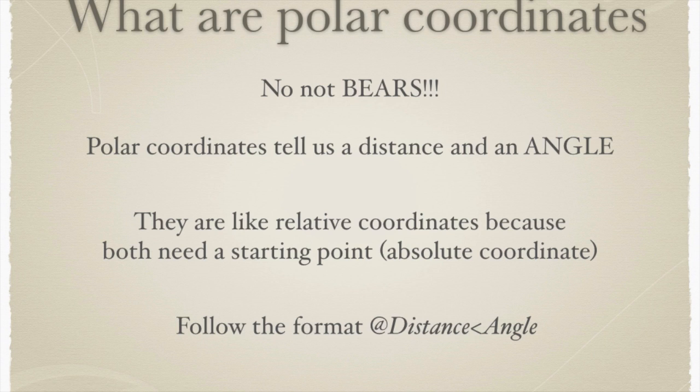It has an @ sign, then the distance of the line you want, then the angle sign, which, if you look at your keyboard, is over the comma key, so you hit shift. It's also known as the less than key, and then the angle. So let's talk a little bit about the angles.